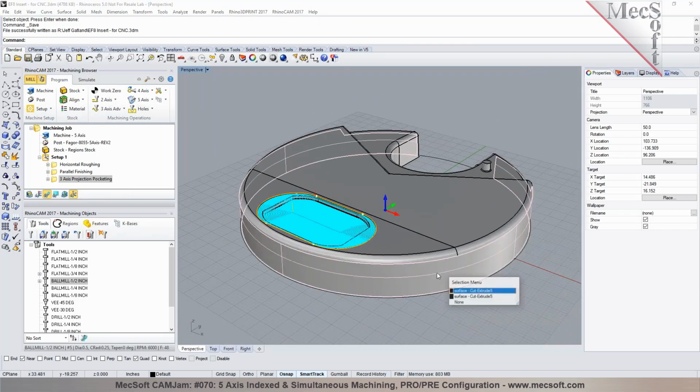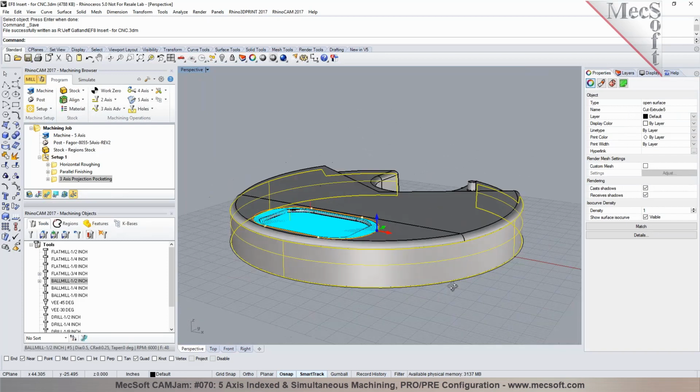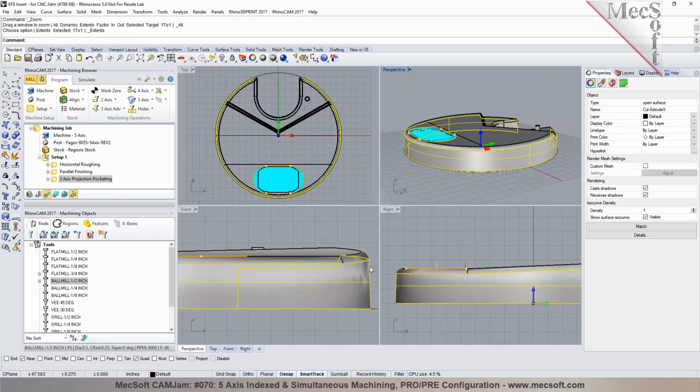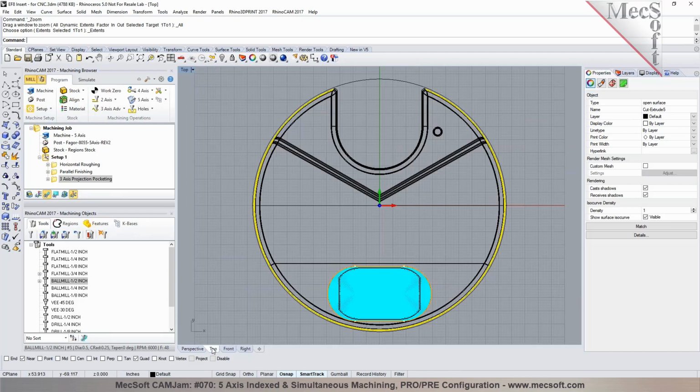Now let's look at machining this one here, right? This particular surface has a draft in here, right? That's the one you were concerned about, right? And a long reach tool will not be able to cut to it. So you want to basically use the side of the cutter to cut it, and then you want the tool to tilt, right? At an angle. Am I correct, sir? Yep. Okay.